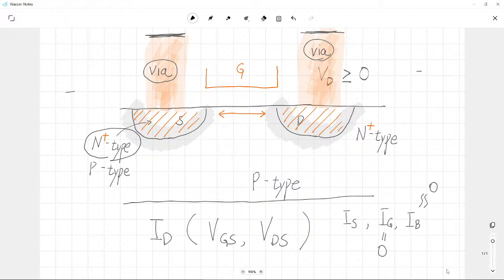So now we can find, within a very good approximation, that the source current is just the same as the drain current, and only the sign is changed. Of course, what is the sign? The usual sign for ID and IS, drain current and source current: usually the drain current is positive and the source current is negative.